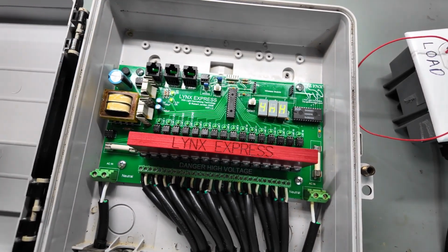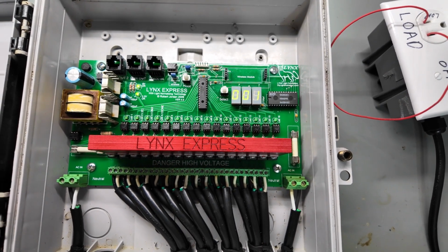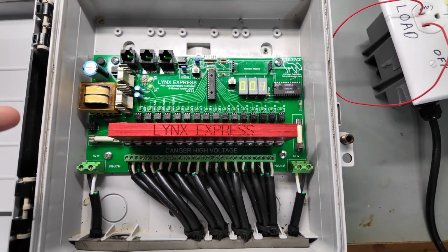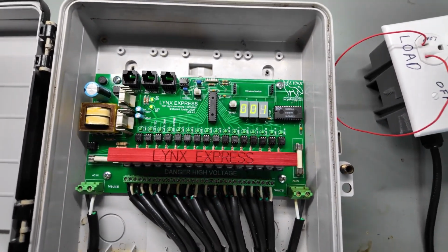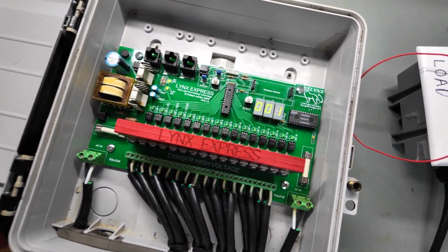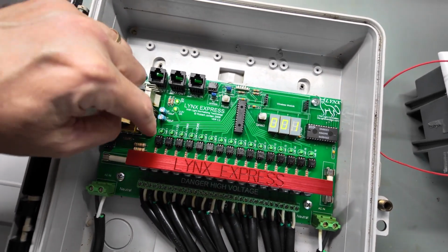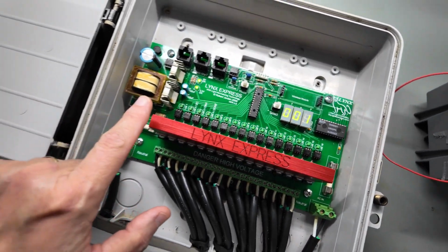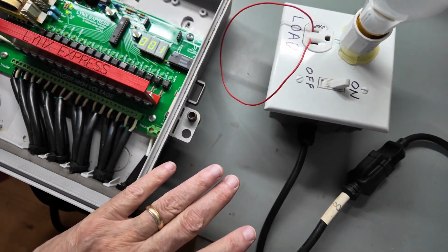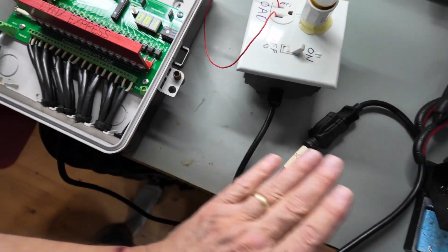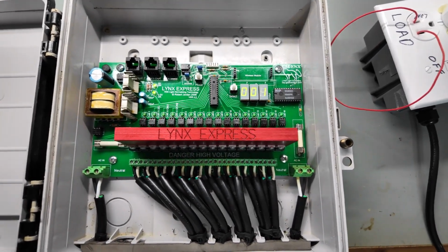So we get 5 volts and 3.3, and we have a boot up going. Lynx Express, 60 hertz, channel 1. 60 hertz because these were designed to run at 60 hertz, or if you program it, you can tell it to run at 50 hertz, so you can use it on 50 hertz systems. Channel 1 means that DMX channel 1 is the first channel of this controller. So channel 1 through 16 DMX, and then if you had your next controller, you would program it to 17, it would be 17 through the next 16, and so that's how you adjusted these. You could have multiple of these on the same channels, by the way, if you were mirroring things.